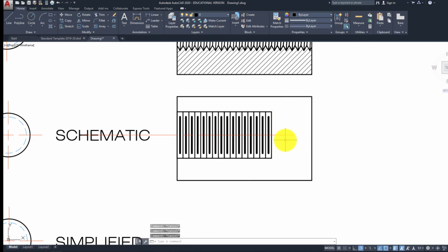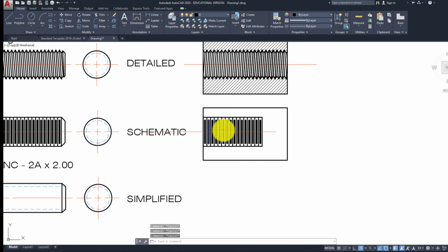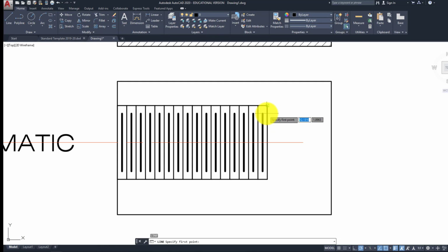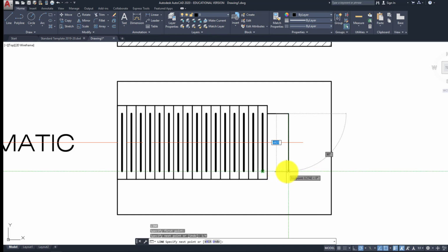What you need to show is actually that drill, how you drill it out at the minor diameter and then you tap it. So right here we could say, this was the length, whatever it is. I'm not going to show that, but right here we actually want to show, and I've seen it in many books, that it's supposed to be a fourth. You're supposed to go a fourth extra. So imagine this being the hole that was drilled first, if you want to picture that going here, and then the tap goes in and actually threads this.